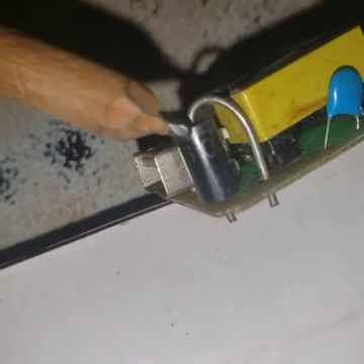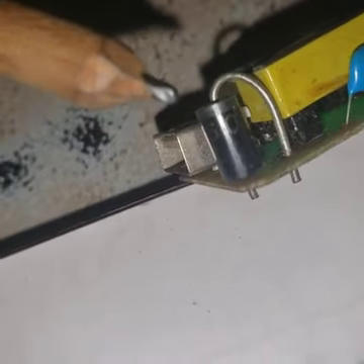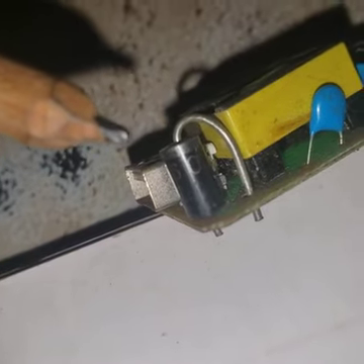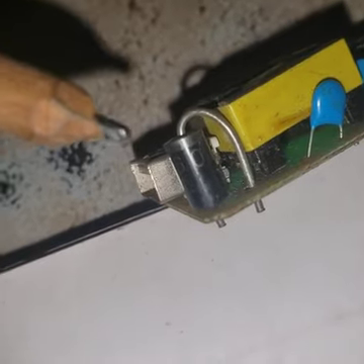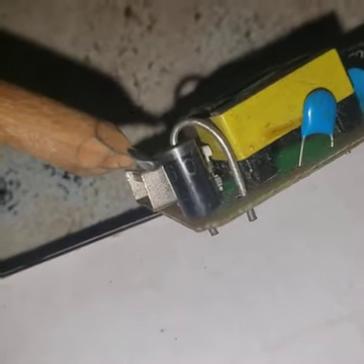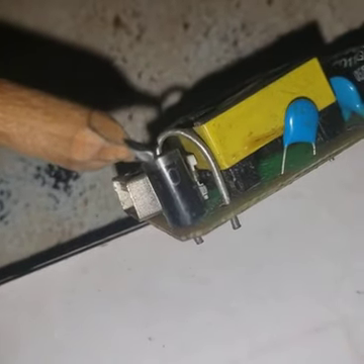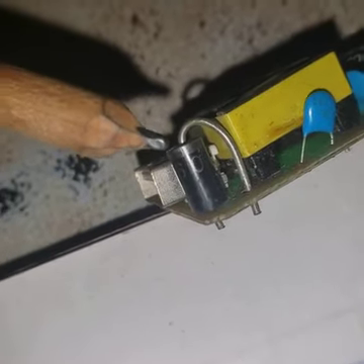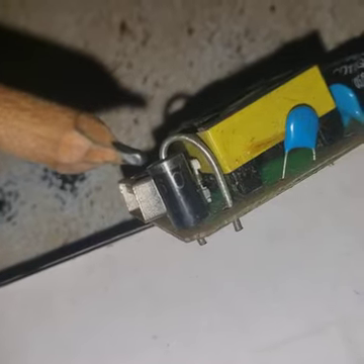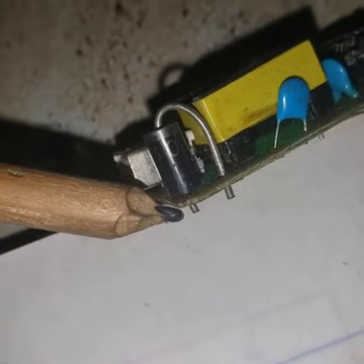This junction here is known as the cathode, the negative side. It is always marked with a stripe on the body, and you are seeing the stripe here. All these other areas are black, then up here you get a stripe like a silver coating on the body. So that is the cathode, the negative side of the diode. Then this other side here is the positive side, the anode.